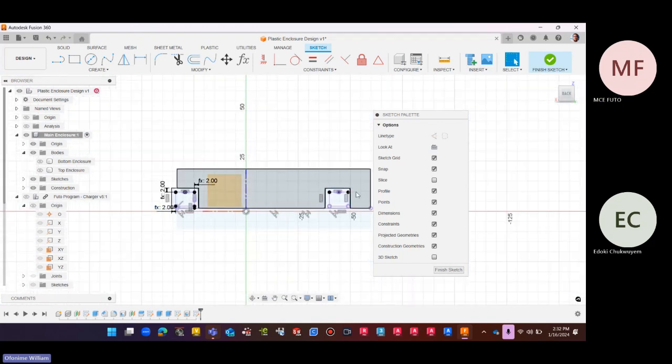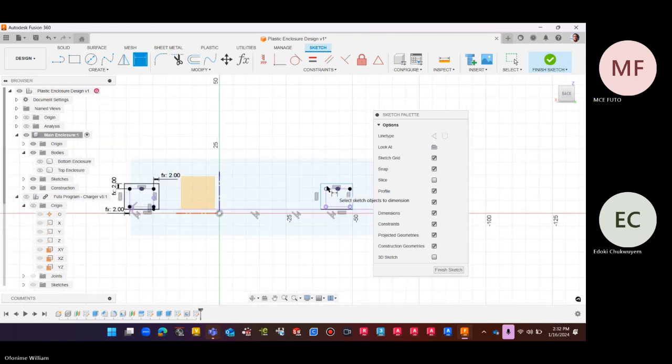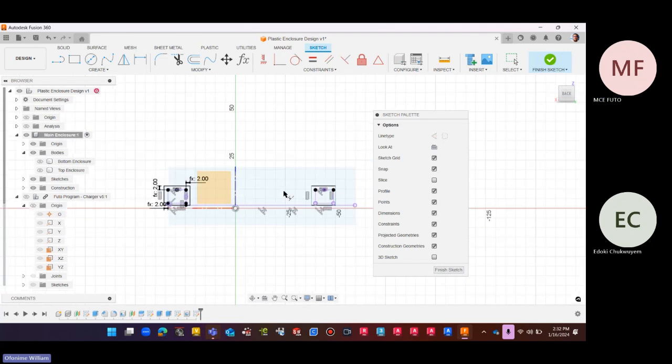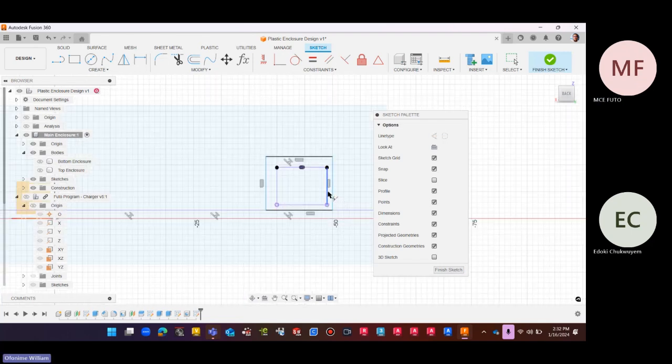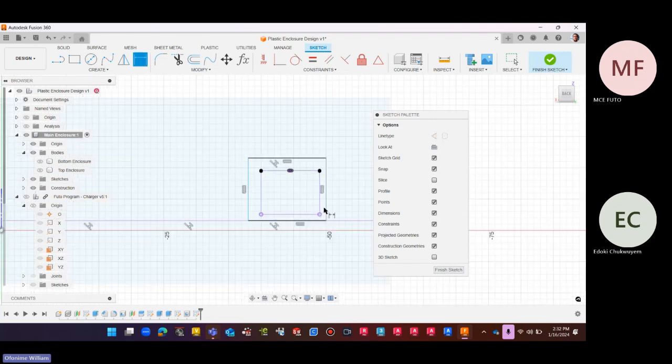So for these other aspects, we do the same thing, but this time around we just do relationships. You could just say, let this height and this height be on the same level. So click on collinear, click on this point, click on this point, right? That one has settled. The next one is this wall. This one will require a dimensional constraint now to actually tell the magnitude. So I'll say, okay, click it up.